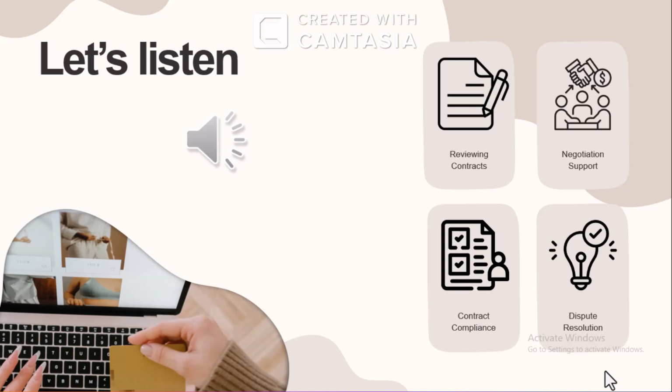Yeah. Excuse me, the SMT machine stopped due to a vacuum pressure low error. We found a loose vacuum hose. See? I got this. Good job.